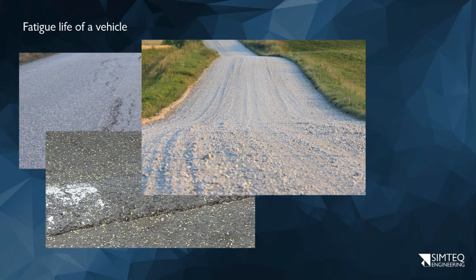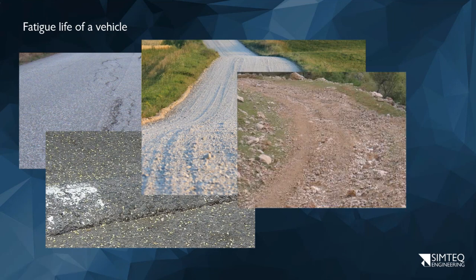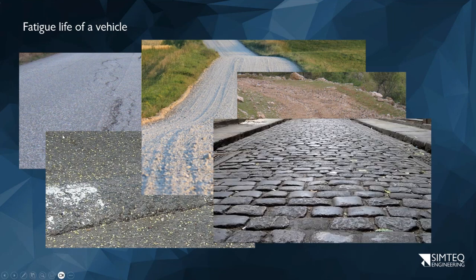But we can also drive over speed bumps, light gravel loads, extreme gravel loads, and if it's severe off-road vehicles, it can go a lot worse than that as well. And each of these will have a dramatically different fatigue life. It may even get to the point where different components actually fatigue based on how the load is transferred.